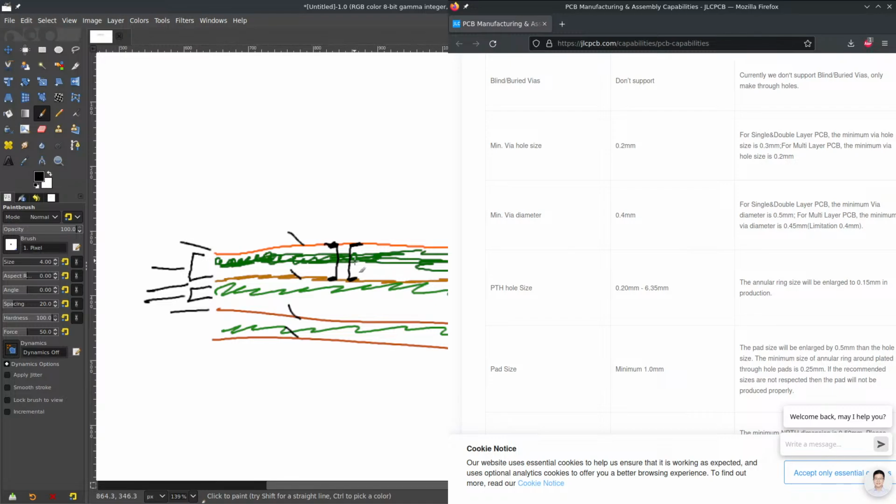They drill the hole, and then they put a little piece in there that's the conductive copper, and then they put the cap on it, which is actually part of the copper layer. I don't know the whole details of that process, and I was trying to find information on it, but I couldn't quite find how it works beyond that. I do know there are options to fill it with solder paste for more current capability that are available out there.